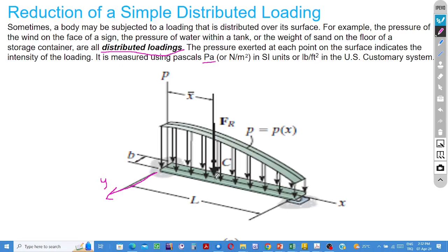If the distributed load has such characteristics, then it is common practice to multiply the distributed load, which is expressed as surface pressure, by the dimension of the contact surface parallel to the axis along which the load is uniform.